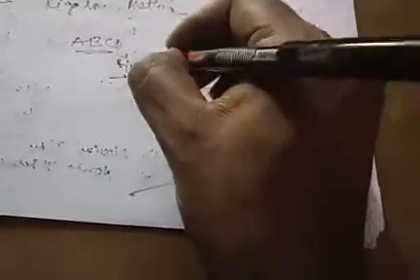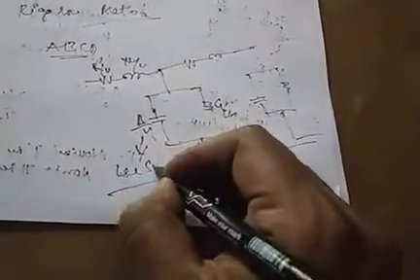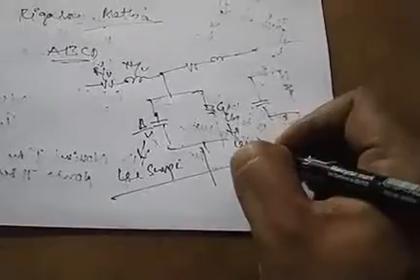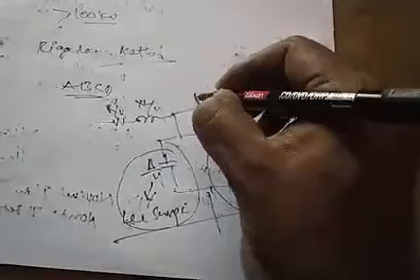So how does the model look? We already discussed how the model looks. This is the capacitance. This is the inductance. See, this is the model representation. The n number of divisions we already discussed. XL by n. This is B by n. This is G by n. This is nothing but leakage susceptance and leakage conductance. This is due to the capacitance existence. This is due to the leakage current. R by n, X by n.